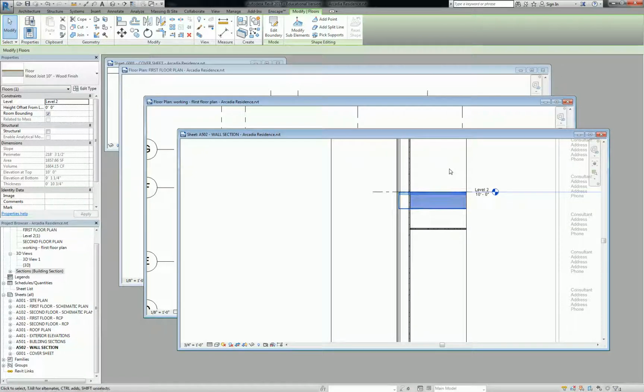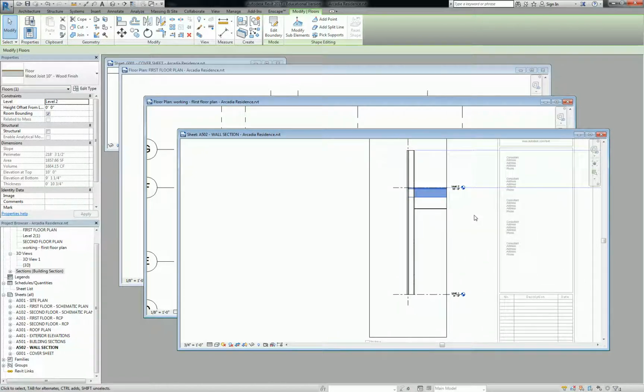We are responsible for making sure that whatever is communicated here matches whatever has to happen in the detail level. And then when you go to the detail level, it becomes a little bit more fleshed out, and you get to see everything. You're basically increasing the scale of the drawing to where you can see how it actually goes together. Okay, so that's the point of your building section, then wall section, then detail.